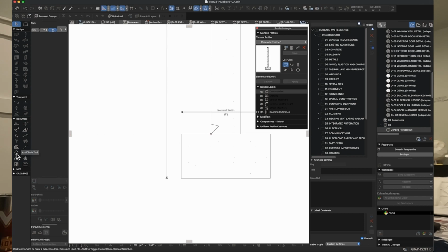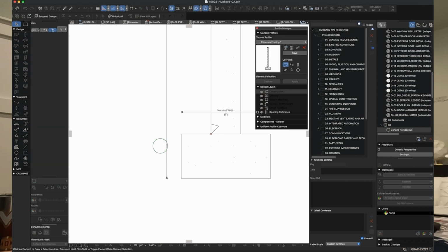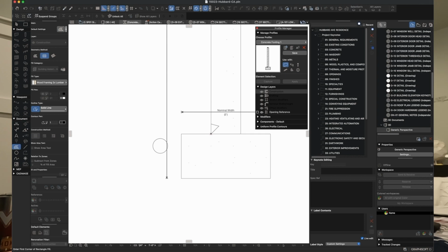So what we're going to do here is I'm going to take the circle tool and go ahead and draw a 4-inch diameter circle. Obviously it uses the radius for selecting that. And as I do that, you'll see the little arc coming out. We're just going to close it right here at the end point so that we get a circle.